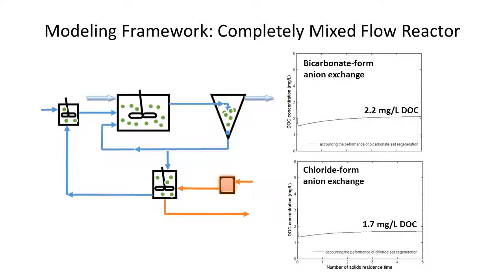And then I have a student who's looking at the completely mixed process. So completely mixed for the contaminant removal, completely mixed as well for regeneration. But the way this is done is, the contaminant removal is on a continuous basis, whereas this really operates on a sequencing basis, sort of intermittent. And then she's doing some nice work trying to account for the different regeneration ability of the chloride versus bicarbonate in terms of both a capacity point of view, equilibrium, and then a kinetic point of view.